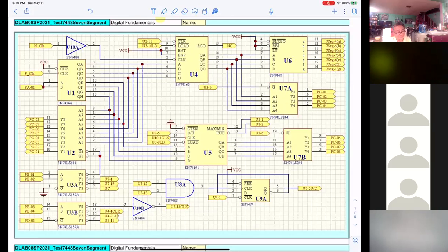When you start counting up, and after you're done counting up, they're supposed to turn this one to logic 1 in order to count down. However, now they're not counting down. So you have to troubleshoot it, looking at pin 5, see what logic. They're supposed to be 1, but they're not 1.